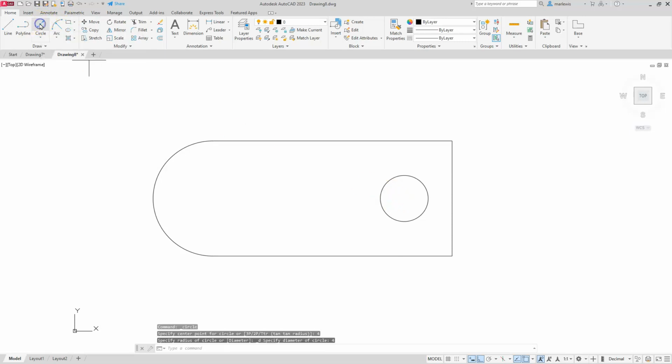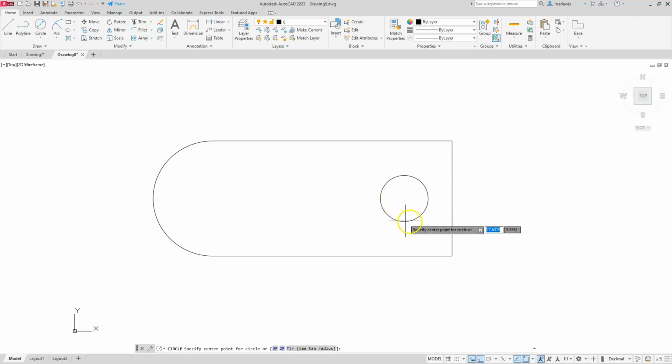Okay? Now let's go ahead and create another circle just like that. We're going to go to our circle center diameter. This time, I'm going to highlight the center, and you'll notice that on mine and probably on yours, the center is not coming up. Let's go ahead and make center one of our running OSNAPs, which is here, and it looks like it is turned on. So let's see how we can get that to show up. Let me click here. And now if I go to the circle, and you'll see that I'm not left clicking on it, I'm just touching parts of that circle. Once I get the center, I want you to stay on the center for a second. And then I want you to exit out of that circle quickly and at a diagonal. So I'm coming out this direction, and I'll come down here. Once I have my tracking symbol, I'll type in 8, enter.